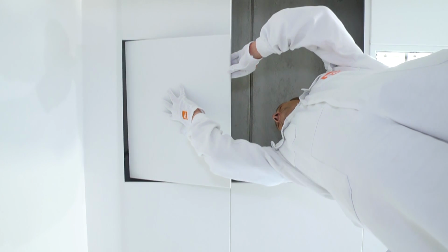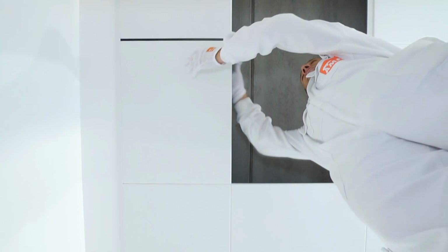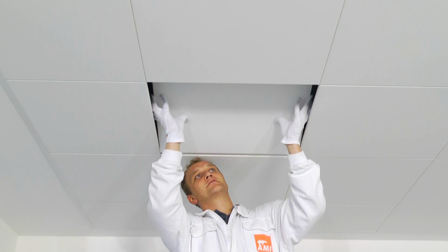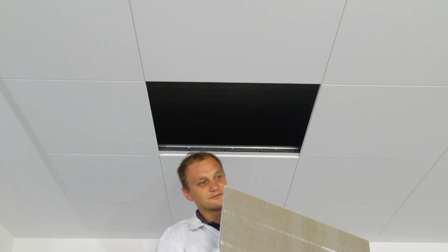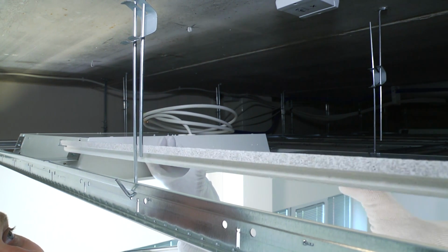The corner tiles, as well as both adjacent cut tiles, are demounted from the penultimate row. Every tile in this system is individually demountable for maintenance work. It is sufficient to slightly raise the tiles on one side until they can be pushed over the main profile. However, there is risk of damage in the areas around the hangers.